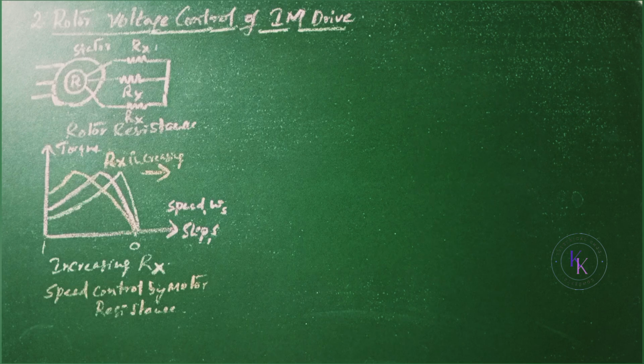Because of the availability of the rotor winding for changing the rotor resistance, the wound rotor offers greater flexibility for control, but it increases the cost and needs maintenance due to slip rings and brushes. The wound rotor motor is less widely used as compared to the squirrel cage motor.